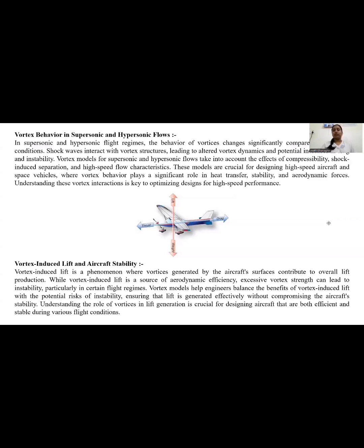However, excessive vortex strength can lead to instability, particularly in certain flight regimes. Vortex models help engineers balance the benefit of vortex-induced lift with the potential risk of instability, ensuring that lift is generated effectively without compromising aircraft stability. Understanding the role of vortices in lift generation is crucial for designing aircraft that are both effective and stable during flight conditions.